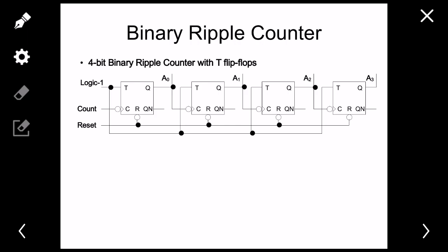The only addition to it is the new reset button right here. The reset button is shorted. You can see all the reset pins are shorted and connected to a single reset pin, right? So for normal operation I'll be putting 1 here so that my flip-flops won't be getting a reset command, or the reset won't be happening.